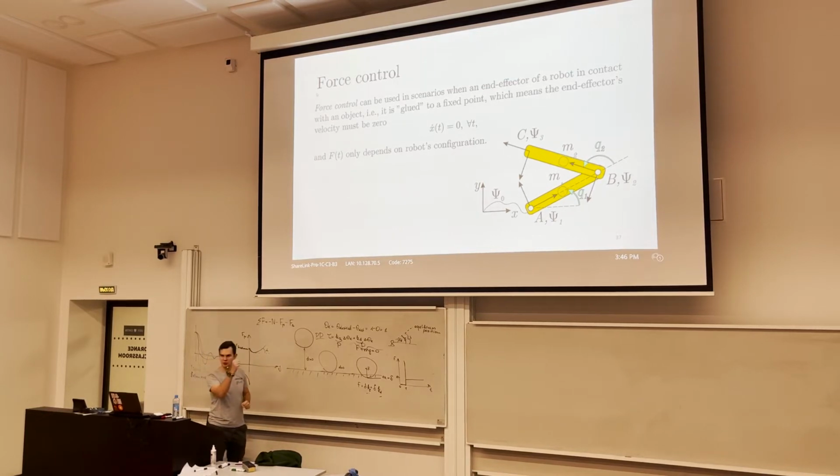Now I use position control. I touched the board, and right now I can switch to force control, and I can apply force. So force control can be used only there. And this is why force control actually is something ideal, and pure force control, we do not use pure force control, only in combination with the position control, which is something called hybrid position force control.